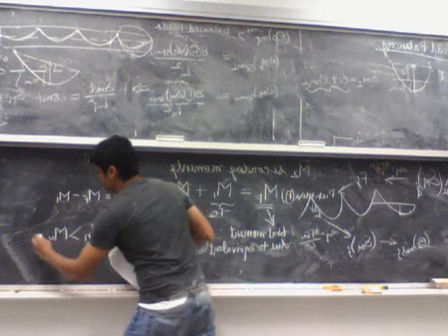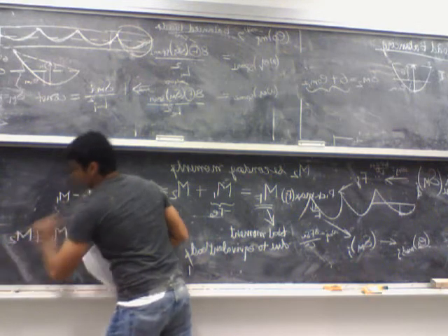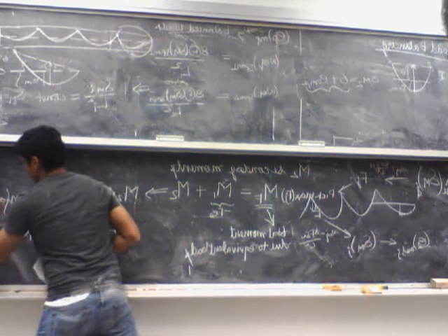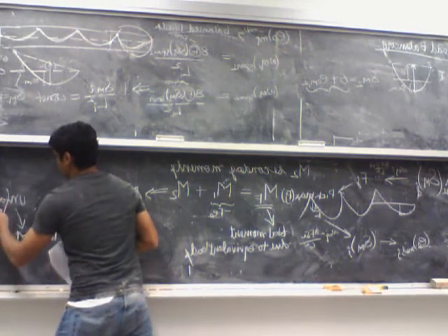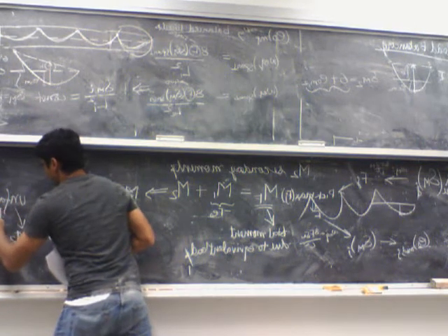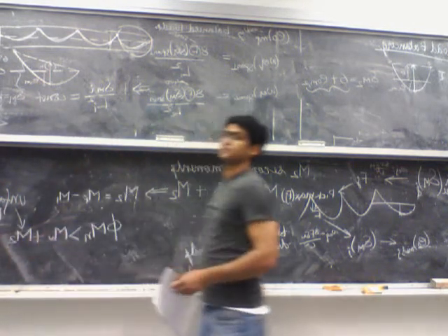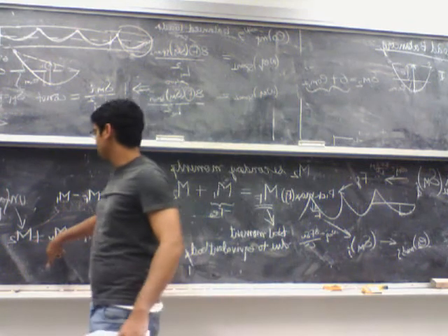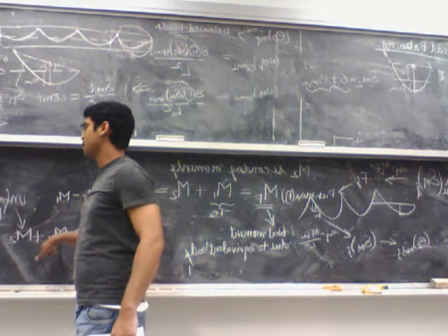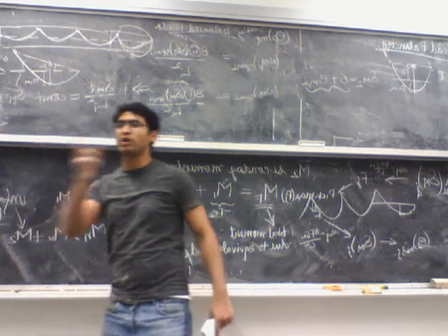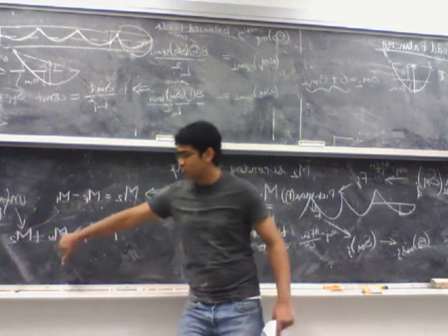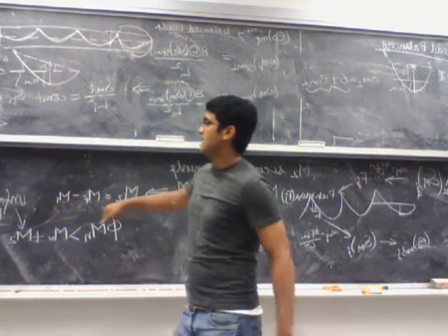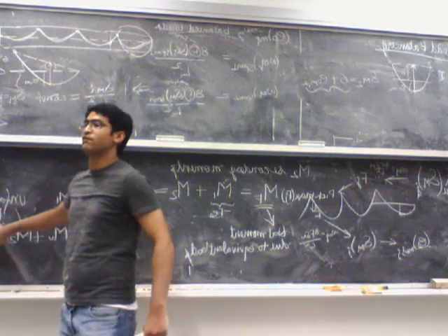continuous beams or an indeterminate beam, you also have another term of M2. And this M2 is based on unfactored F, that is the effective pre-stressing force. So this Mu has the factors on all the loads, so it's 1.2 times self weight plus 1.2 times dead load plus 1.6 times the live load. But this M2, which is the secondary moment, is actually unfactored and it's due to the effective pre-stressing force.